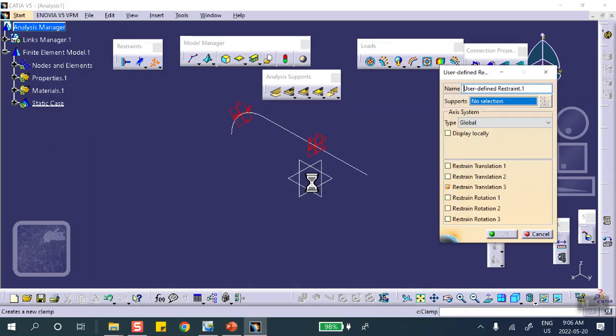User-defined restraint. Let's clean this up so that we start fresh right there. No displacement in direction Z. Rotation opposite. So if this is checked, this must be free. If these are free, you can see they are free. These must be checked. No part marks for that portion. Okay. Let me give you an idea. If this problem was given to you, I would say 20 marks. Having correct restraint would be what, 4 marks? No part marks. Okay.